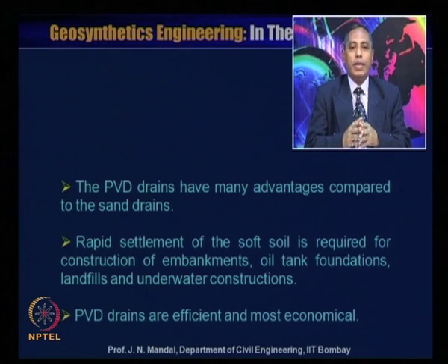Now, prefabricated drain has many advantages compared to the sand drain. Rapid settlement of the soft soil is required for construction of embankments, oil tank foundations, landfills and underwater construction. Sometimes the sand drain may not be continuous if the mandrel is withdrawn very fast.